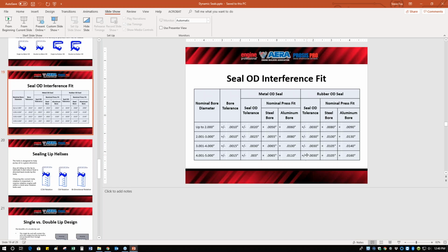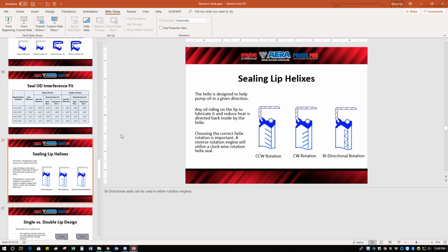So again, let's say you have a seal that feels like it's too loose, this kind of chart can help you go, do I have the right interference on this? Is there something going on with that seal? Has it been used before? And now it's got a set to it. You can kind of understand if it has the right interference or not. Maybe you got some cheap offshore seal you got a great deal on. You may not get the deal you think you're getting because the interference isn't right on it. And this thing's going to want to pop out in operation.